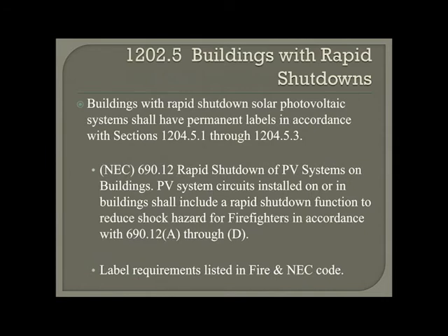Buildings with rapid shutdowns. So every system that gets installed in Lincoln, as per where you see the NEC up there, requires that emergency shutdown system. So any system installed in Lincoln, regardless of the type of structure, will require it. So then that way the fire department can go and disconnect that level service. We'll disconnect the LES side of the service to try to de-energize the structure before we continue to try putting something out that may be burning. So that'll always be required, and the signs associated with it will always be required then also.